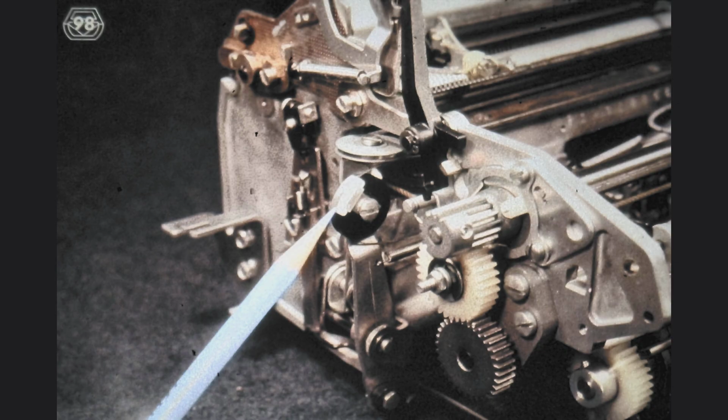As soon as you have removed the rotate tape shoe on top of the rotate arm, your tape is free, with the exception of the anchor screw on the right side of the carrier, and by now you know how to handle that. Prior to loosening the anchor screw, take off the tilt spring tension so that the tilt tape cannot snap. Now we could go right back to reinstalling the rotate tape, but rather than do that, let us first continue with our exploratory disassembly.